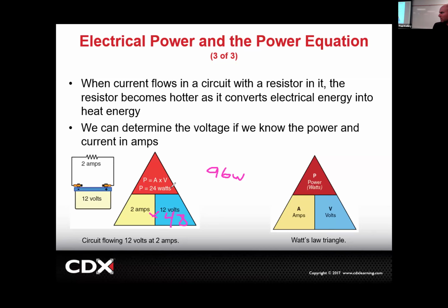So if you can imagine when they started wanting these EVs to actually move the whole vehicle, and especially move it quickly, their option is either A, jam tons of amps in there, which you can do, but amps are kind of hard to handle. That's talking about big conductors, right? Big wires. So instead, they're like, hey, let's increase the voltage, and we can get power out of it through high voltage. But then we're running big insulation and high voltage cables, and we've got to train the techs a little better and stuff, right?